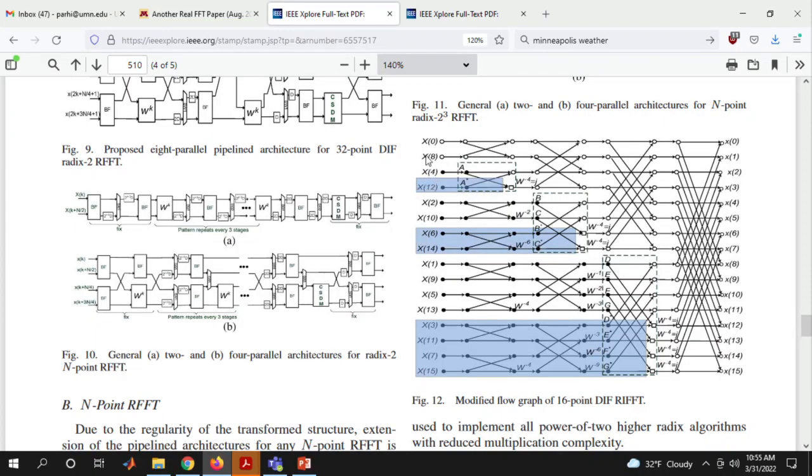So in other words, this x0 to x15 is a conjugate symmetric sequence, and that means when I'm computing the IFFT, by the way, you probably remember the inverse FFT is very similar to the FFT. All you have to do is take the conjugate of the twiddle factors.